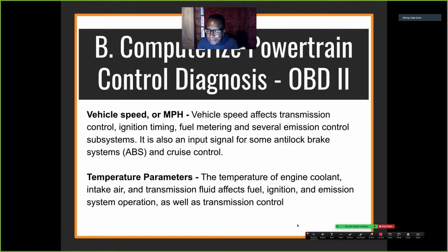The vehicle speed sensor tells the computer to shift the transmission and apply the right amount of fuel. But if that vehicle speed sensor says you're decelerating and you're not, because it has a glitch, the computer's going to decelerate and downshift the transmission again. It's going to change the timing, and it might go into decel control, which means turn off the injectors.